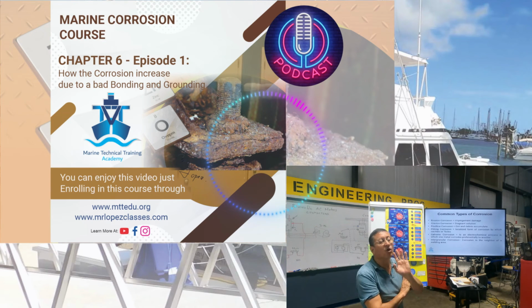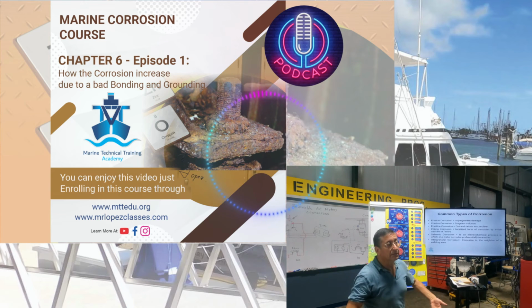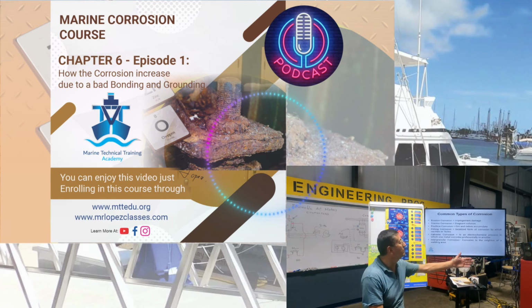Basically, the galvanic isolator is located here: this is the ground coming from the shore power, it passes through the switch selector, enters into the boat and goes directly to the ground bus bar. Before the ground line enters into the ground bus bar, you cut it and you insert the galvanic isolator. Of course, after that, the ground bus bar shall be connected with the bonding system, and the bonding system finishes in the sink.